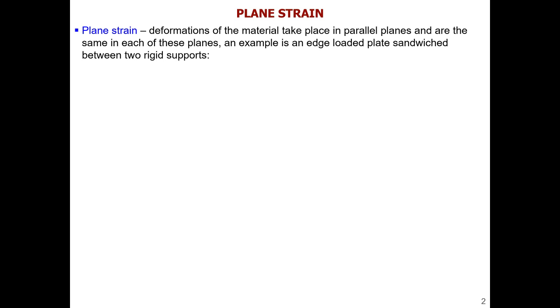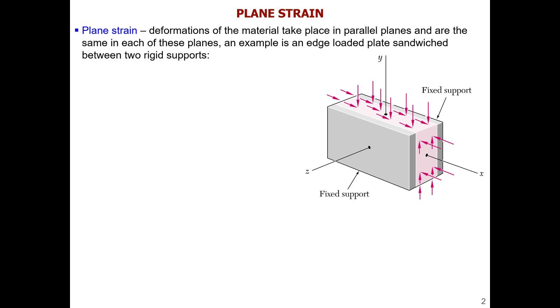First of all, we will be simplifying things and talking about a 2D situation, which here is plane strain. So plane strain would mean that we don't have a deformation developing in the third direction. So we are constrained in 2D. So this is quite possible. For example, we can easily constrain our body or some structural element by some fixed support, some rigid plates, and then we don't allow any deformation, any changes in that out of plane Z direction. We still can obtain deformations in plane because as we load, the material will deform, but only in plane. So we constrain the Z direction.